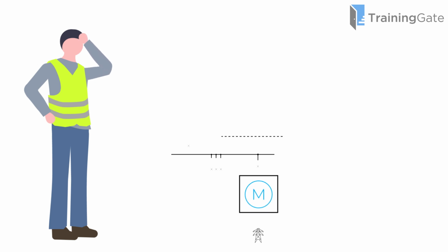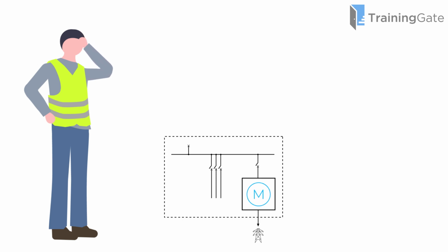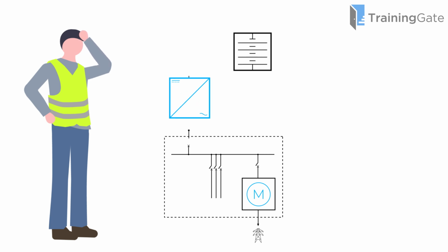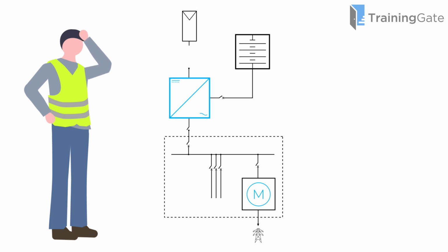To create an SLD, start by connecting the major components using single lines. Include the grid connection, if applicable, main switchboard, circuit breakers, isolators, inverters, batteries, PV arrays, and their respective disconnectors. Then, add equipment details such as names, quantities, cable sizes, and current or voltage ratings. The amount of detail included depends on the diagram's purpose, for example, design documentation, installation guide, or compliance submission.